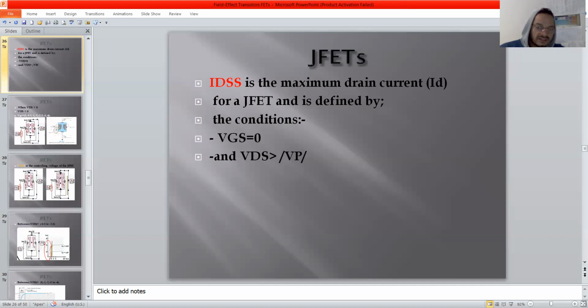Here, let me catch that. Gate volts control the thickness. Gate volts will determine the thickness of the channel. And let's see how. It has two kinds, like I said. Consider an N-channel device: two polarities, N-type and P-type, and two kinds, enhanced and depleted. Let's see what all of these are.